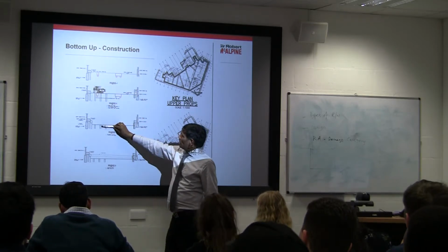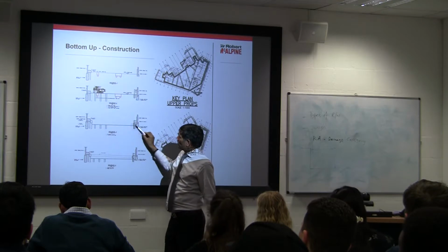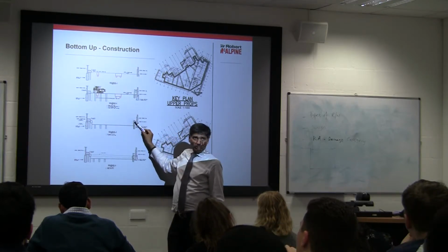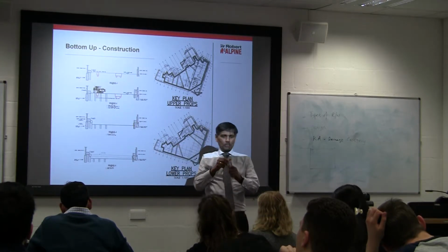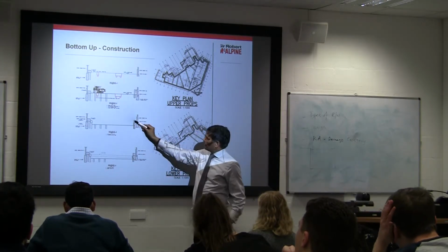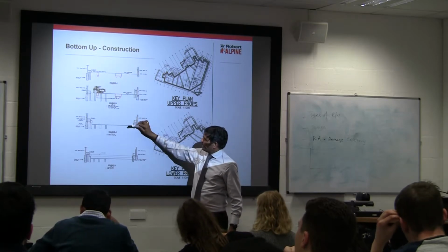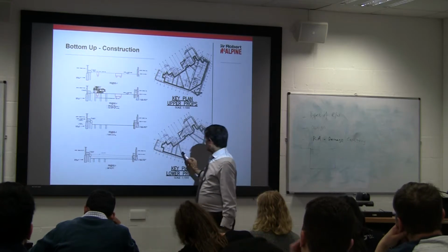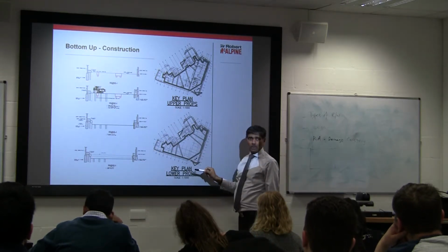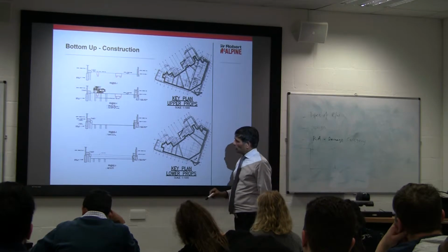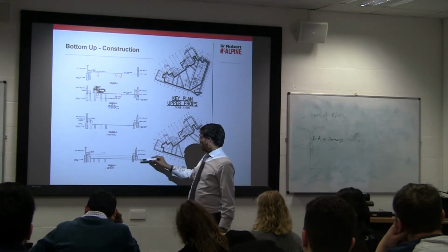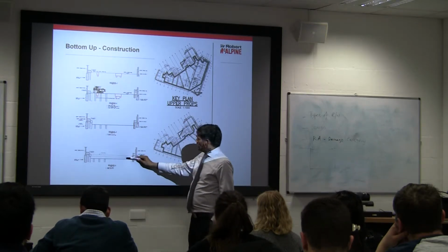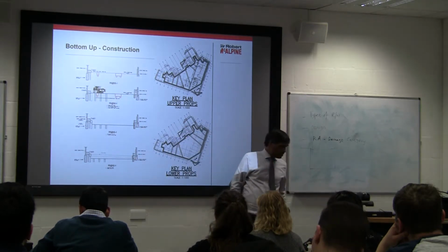Next stage is we actually start dropping the ground after we construct the capping beam. Sometimes you may have to, as I talked about, the plunge column. We insert the steel plunge column, and that will hold the wall by means of rakers or stubs here to hold it. Then we sequentially drop the ground, and then we put a fly-through prop. As you can see, this is the plan view of the props. Spaced nicely for the plant to move, and then also gives you logistical operations for all other things that are going on the site. And so once you install the prop, dig further, and then